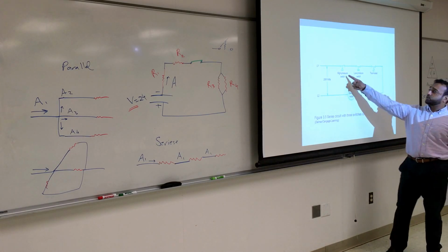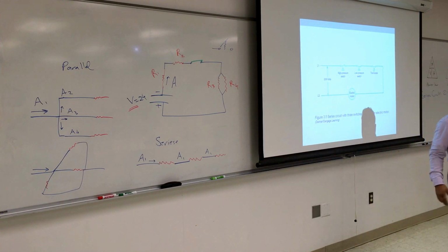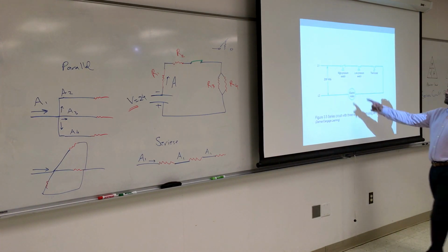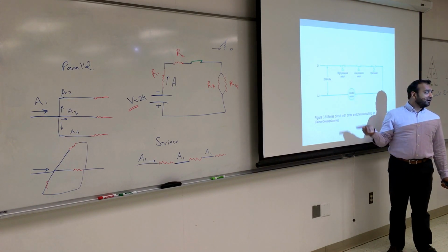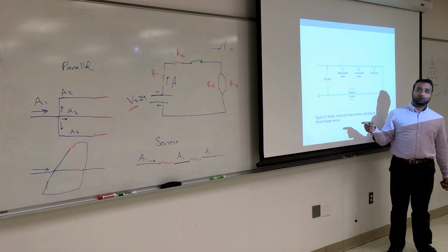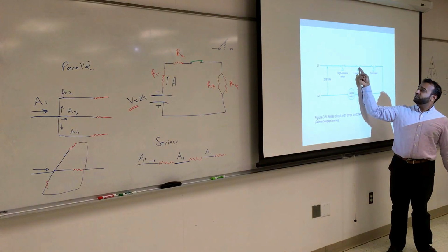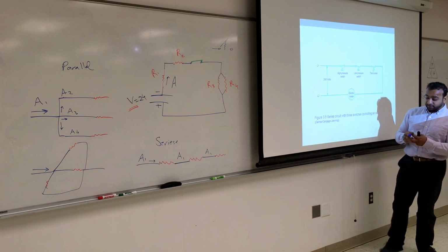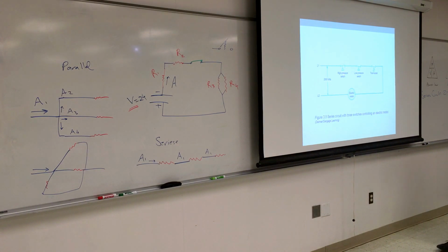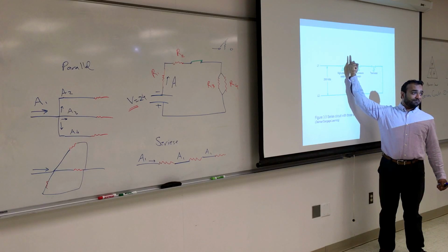So this is a high pressure switch. If the pressure in the system, I'm assuming it's going to be a steam boiler, is too high, this will open up and it'll cut off the circuit from the entire control. If the pressure is too low, it will engage. If you notice the position is different, do you see the little differences here? Yeah. So the high pressure, inside, this needle will go up to push up and disengage the circuit.